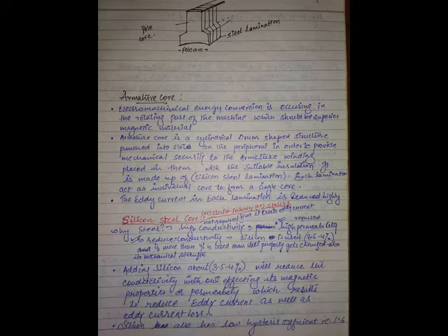Armature winding: conductors are made into turns, turns made into multi-turns, multi-turns made into coils, which are arranged in series, uniformly distributed on the armature peripheral. That's the basic definition of armature winding. We'll discuss that later. This is one coil connected to two segments. If there is one more coil, like that there are n number of coils which all should be connected in series through commutator segments, so you will have many segments on the commutator surface.